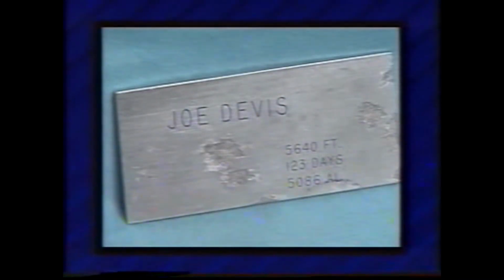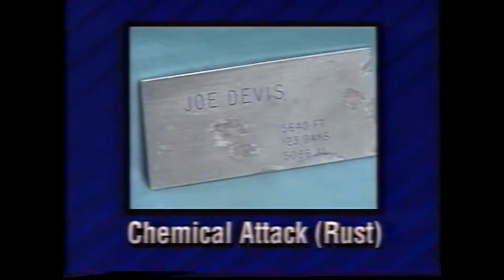Atmospheric corrosion of metals by general chemical attack is the simplest and most common form of corrosion. In iron and steel, it is commonly called rust. White rust forms on zinc and aluminum. General corrosion occurs in the atmosphere, in liquids, and in soil, frequently under normal service conditions. The rate of attack can be rapid or slow. The metal surface can be clean or covered with corrosion products.